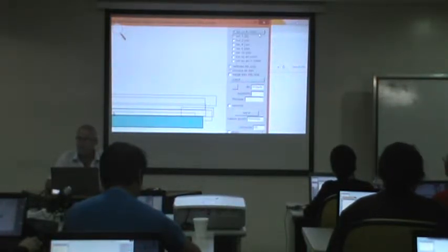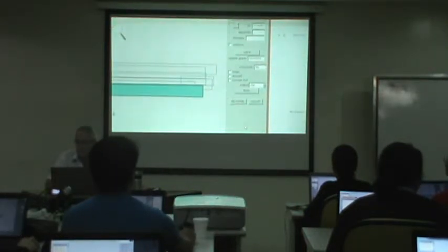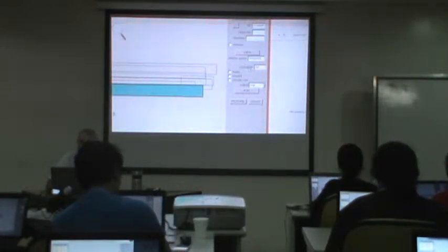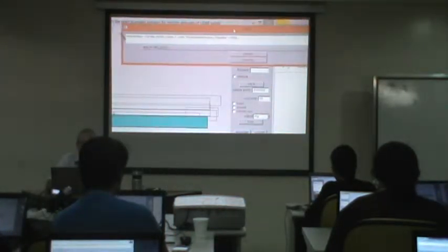And because I'm now computing a boundary individually for every one of these LAS files, I can again run on multiple cores. Later we're going to talk about what this concavity value means, but right now we're just going to leave it at 50 meters. And then I'm pressing run, and I'm checking my command line.